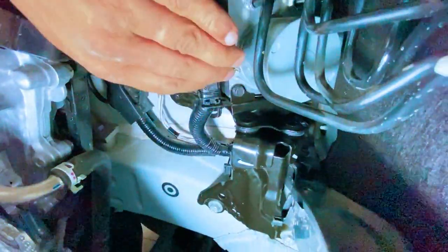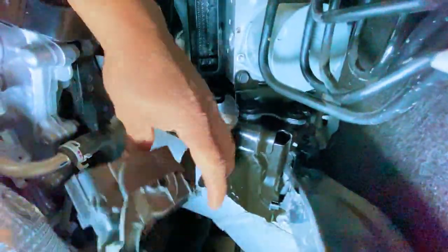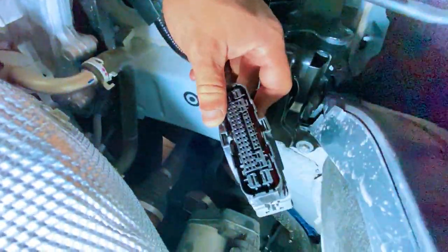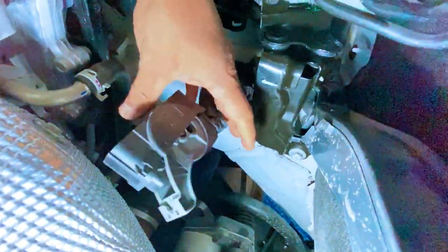When the ABS motor relay is operating, the skid control ECU monitors the motor circuit. If the current becomes higher than the specified threshold, or if a short circuit is detected in the pump motor drive circuit for the specified time, C142719 can be stored. This is why C052F14 and C142719 together are very important.